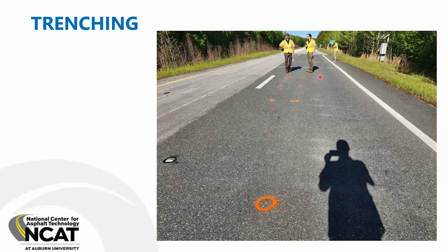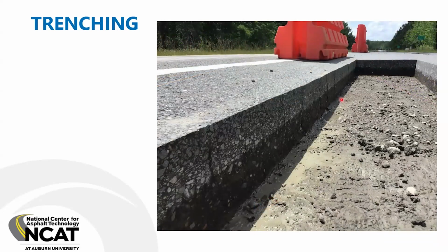Okay, and then in the background, we've got a full lane width transverse trench that ties into a longitudinal. So we've got a T-shaped trench there because that area was also of interest. But when we cut those with a wet saw, we pull all these slabs out, you can see all of these transverse cracks that are just popping out at you. And not all of them are visible from the surface. So like Buzz says, when you have those fatigue cracks, they'll start off at a certain interval, and that'll be fairly repetitive. And then as the fatigue crack spreads, it'll fill in the gaps between them, and that fatigue cracking gets tighter and tighter until you get that complete pothole formed.